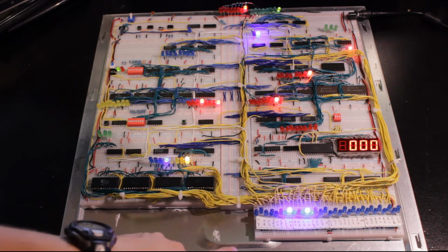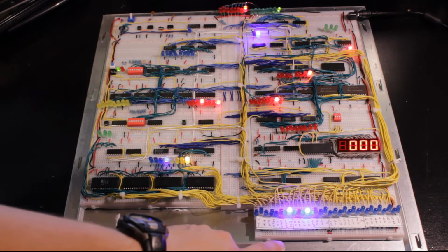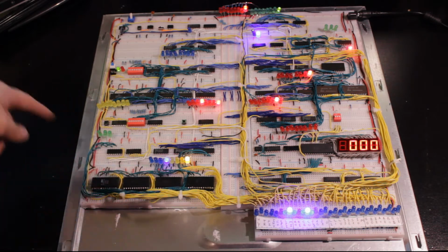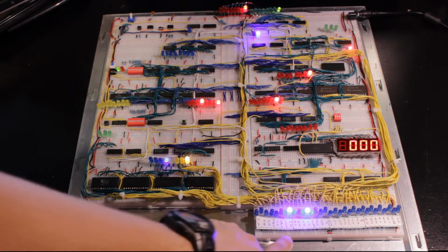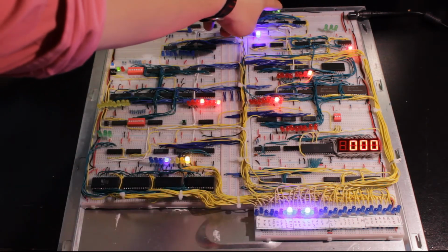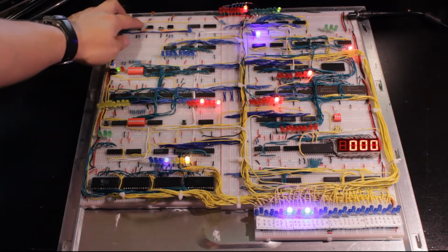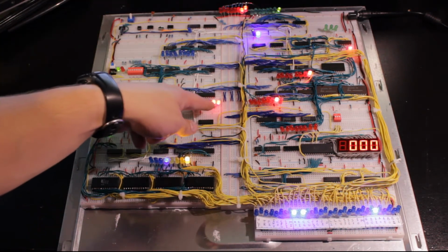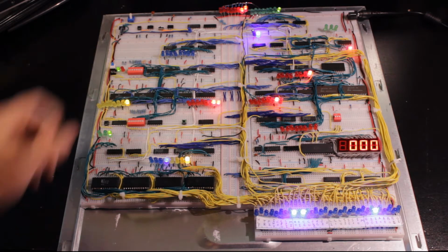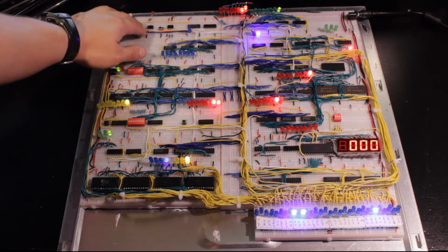Now next, we are executing a fetch cycle because we did an early termination. So we're going to fetch from the counter that value 1, get it in the memory address register. Then we're going to get the next instruction, which is a 0x03 for a store A, into the instruction register.